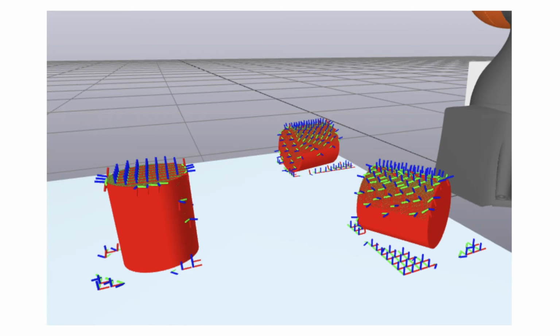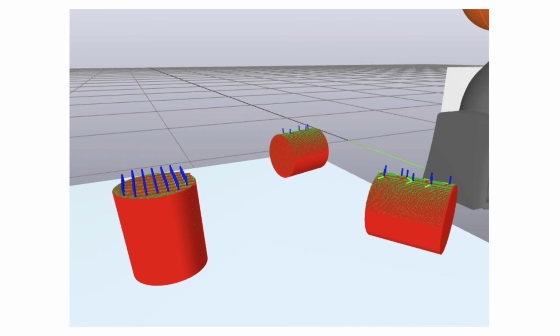So instead, our solution to determining grasp poses was to take advantage of the geometry of cylinders. First, for some pre-processing, we filtered the normals and only kept ones that were sufficiently vertical and off the ground. And because of the geometry of a cylinder, there are only two cases for how they can be positioned, vertically or horizontally. And in both cases, the average position of the vertical normals in the XY plane was approximately equal to the center of the can from above. And so this can be used as the position for a grasp pose.